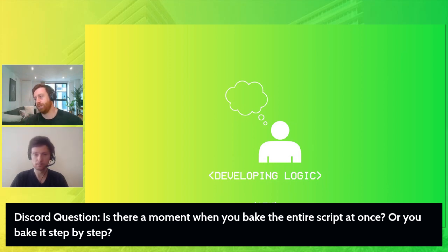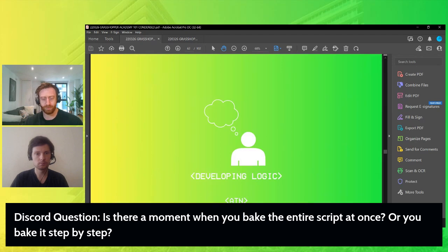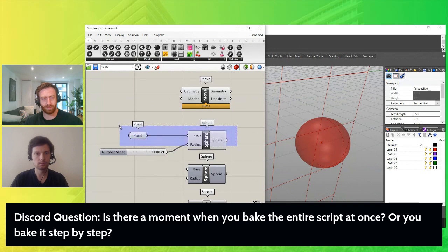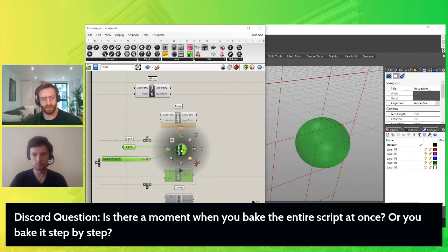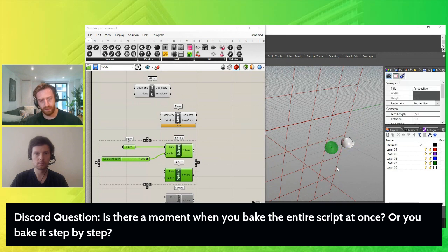Is there a moment where you can bake the entire script at once, or do you bake step by step? Yeah, that's a good one. I very rarely had to bake the entire script, because for example here, I don't want to bake my point and my sphere, but I could. If I select all of this, I can right click on it and hit bake, and all of these things should bake, if I'm not mistaken. Yeah, there you go. My point and my sphere is baked.